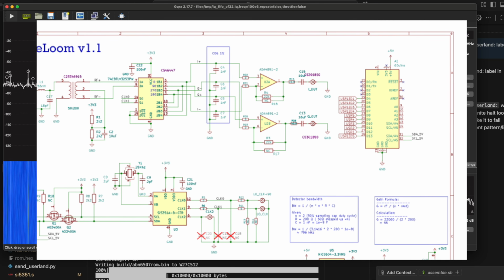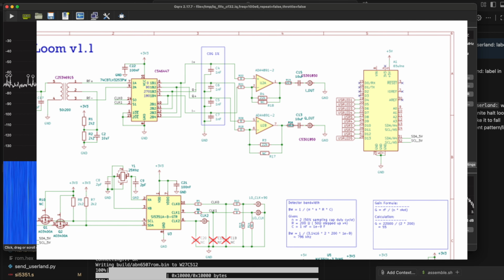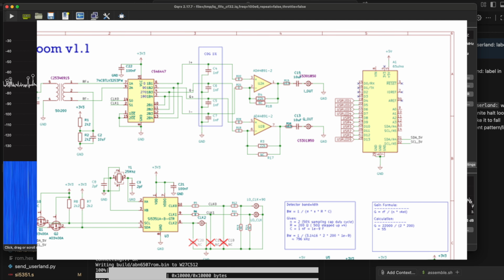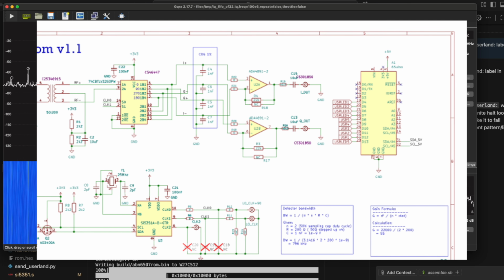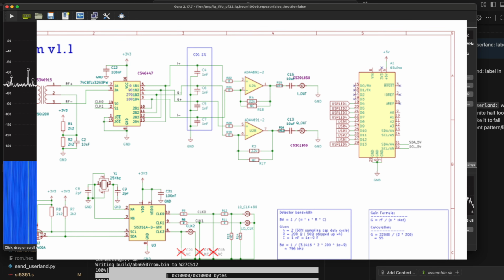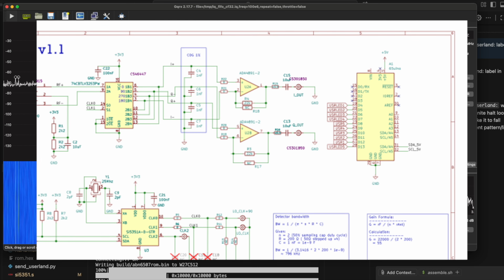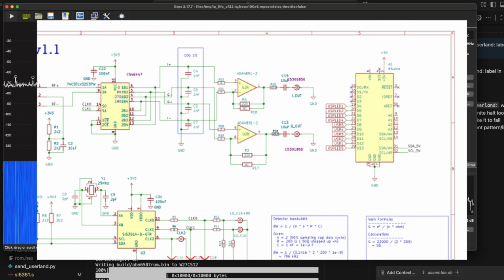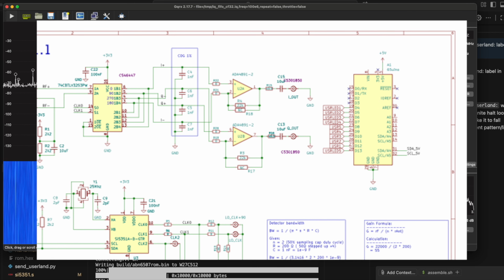Since any imbalance in the signal coming out of the op-amp will cause an amplitude mismatch, it'll also cause IQ imbalance, which we'll see as even worse image rejection. To fix that, we need super precise resistors to set the op-amp gain. Unfortunately, I don't have any 0.01% 47K resistors that we can use to about double the gain from what we